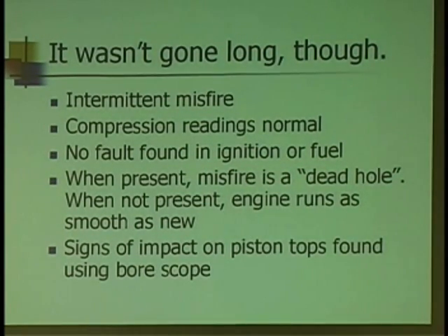And he saw some impact signs on the pistons. You use a bore scope. They didn't take the time to look the first time around. So he told his boss, we need to pull the heads. I think we've got a valve train problem. Wouldn't you guys? So far, I would.